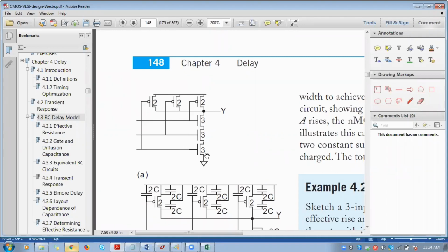If the transistors are connected in series, we add the number of stages. As per this connection, at the NMOS side we have 3 stages and the PMOS side we have only 1 stage. To calculate each transistor's K value, we have to multiply the base K value of that particular transistor with the number of stages.